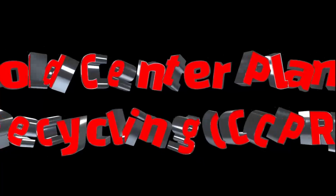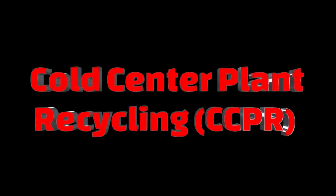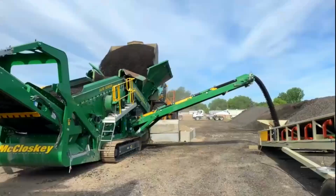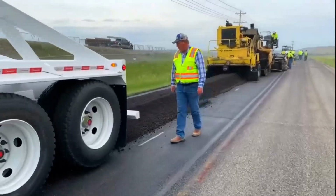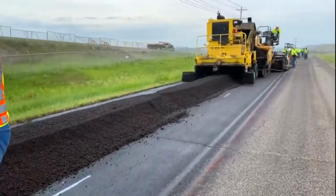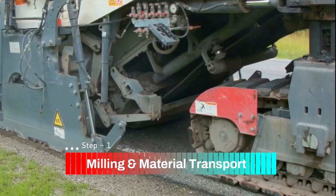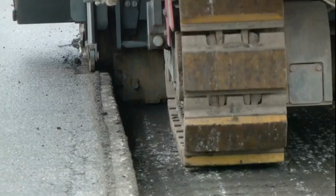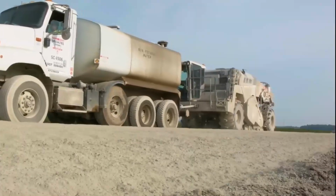Now the second method. Cold Central Plant Recycling, CCPR, step-by-step execution. In cold central plant recycling, the existing road material is transported to a central plant, processed, and then returned to the site for paving. Step 1. Milling and material transport. The old asphalt pavement is milled and loaded onto trucks. The milled material is transported to a central recycling plant for processing.